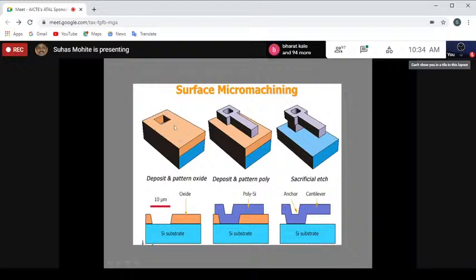Now this sacrificial layer has a window here. So this sacrificial layer was masked and a small window was kept open and it was subjected to light. And then the portion which was subjected to light became soft, and the other surface remained hard, and then this was etched. After etching, a small window was created here, and this is the substrate. Most of the portion of the layer has been retained with only a window that has been cut out of it by an etching process. A selective etching process is used.